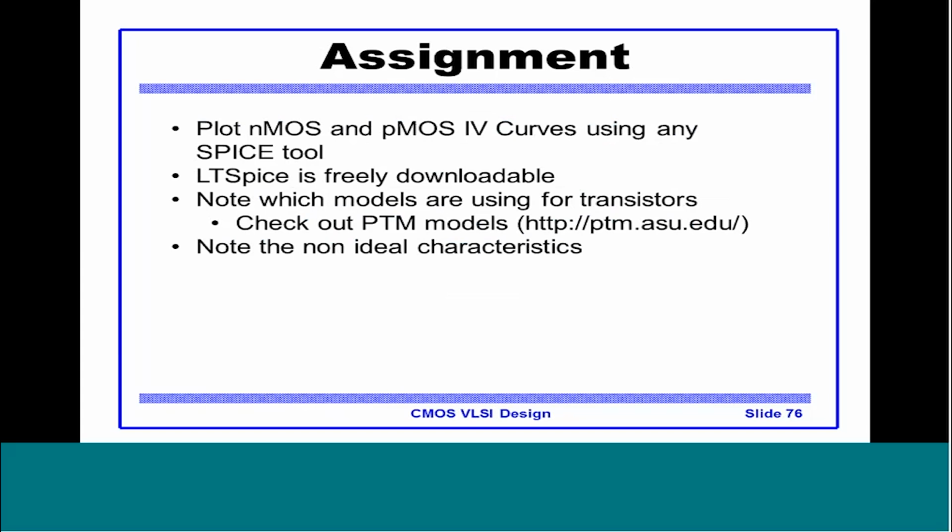One example of a SPICE tool is LTSPICE. LTSPICE is a freely available SPICE analysis tool from Linear Technologies. It has a lot of PMOS and NMOS models, so you can use that to analyze the PMOS and NMOS transistors and plot the IV curve.